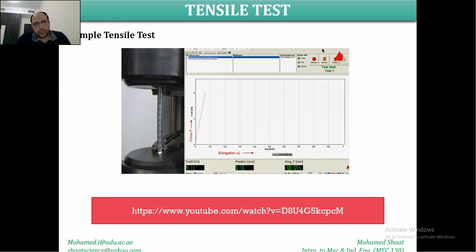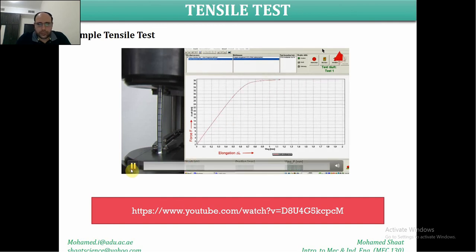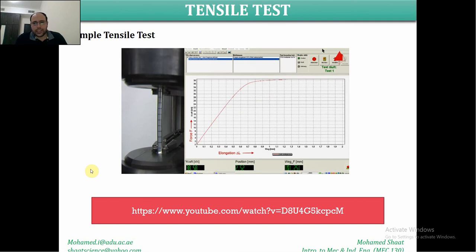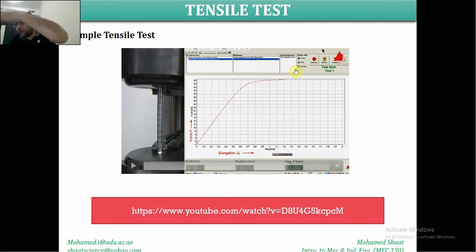The initial linear curve in the force elongation diagram again shows the elastic behavior of the material. But this time, the end of the elastic area is not revealed by a sudden drop of force. As you can see, the force elongation relation is kind of different. With the previous material sample, at the end of the linear relation there was a sudden drop in the force. Then we obtained a roughly constant force over a certain amount of continuous elongation of the material. Then we moved to the plastic region.